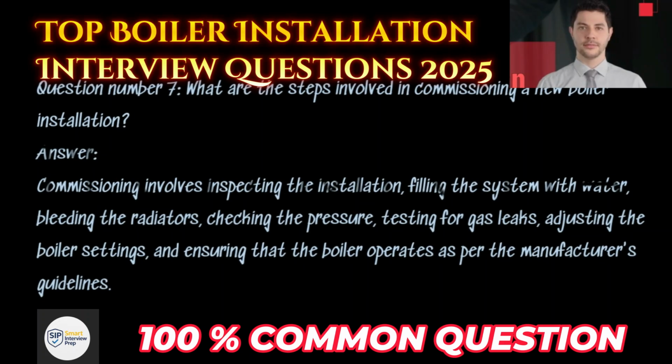Question number 7. What are the steps involved in commissioning a new boiler installation? Answer. Commissioning involves inspecting the installation, filling the system with water, bleeding the radiators, checking the pressure, testing for gas leaks, adjusting the boiler settings, and ensuring that the boiler operates as per the manufacturer's guidelines.